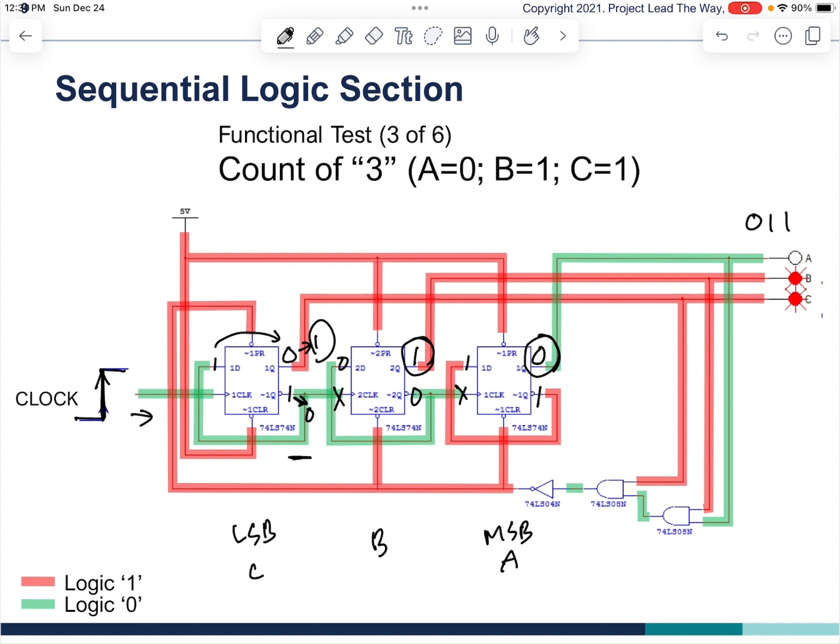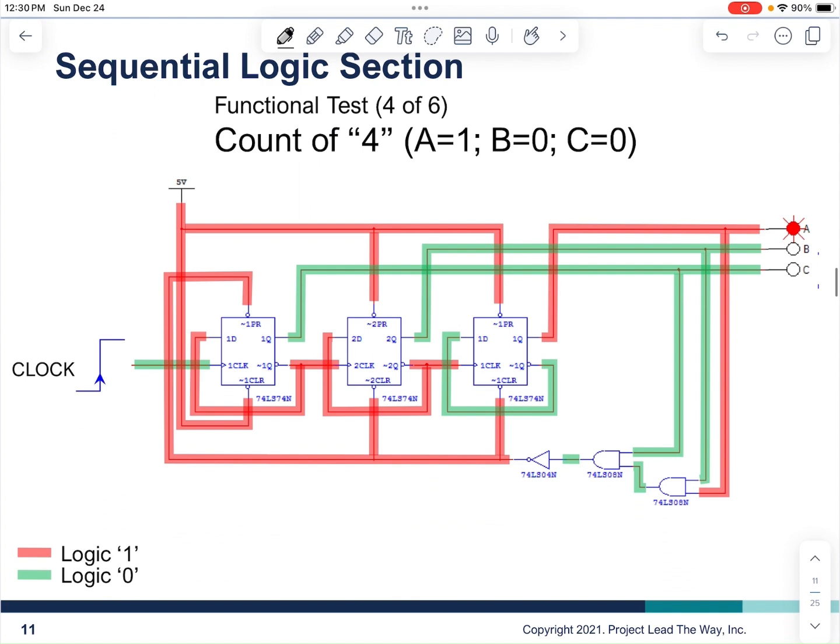Okay, next. So 0, 1, 1. Okay, opposite 1, 0, 0, and we'll have 0 waiting at the door. Rising edge of clock comes in. Okay, and we'll change. In other words, your C is always changing every time the clock comes in. Right? In the B and A, you have to see the clock.